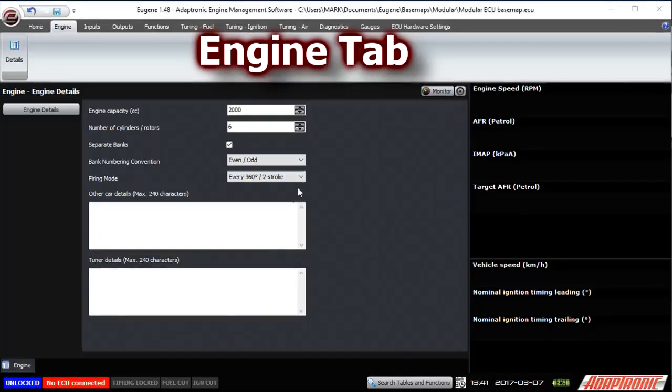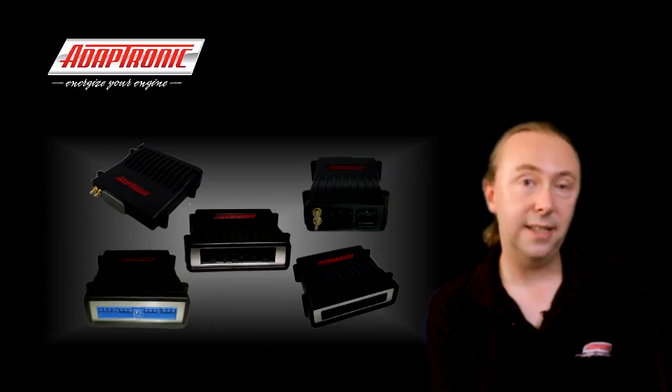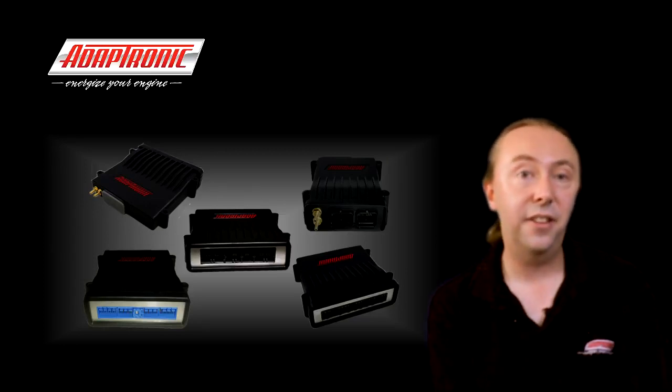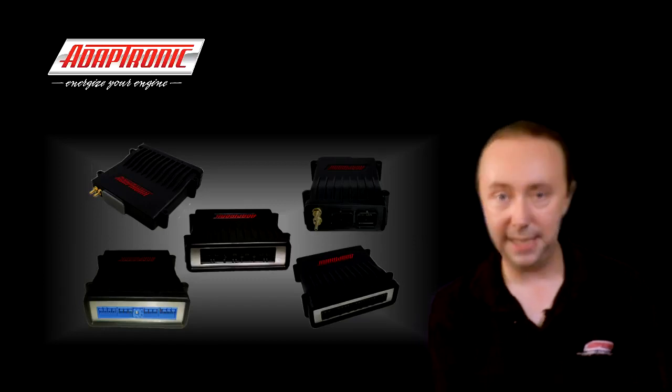Now you can also select whether the halves are defined as being the first half and the second half, or the odd and the even half. So on most V engines you have an odd bank and an even bank, so that's what you'd select. But with some engines they're named where one bank is the first half numbers, like the Allison V12 for example, which has 1 to 6 as one bank and 7 to 12 as the second bank. For that engine you select first half, second half, and that way the number outputs on the ECU can actually correspond exactly to the cylinders.